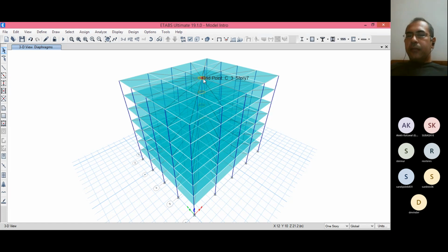Otherwise, if it is a semi-rigid diaphragm, then beams also should participate in the stiffness, and hence your matrix becomes complicated and it is not solvable manually. So for rigid diaphragm, we can solve it manually. That is what I had shown, how they do it manually. And we need to create an Excel for it. Right now I would be doing this analysis in ETABS. You need to do it in Excel. MATLAB is also possible, but if you don't know MATLAB right now, Excel can also do this. For a 7-story building, it is possible to do it in Excel.